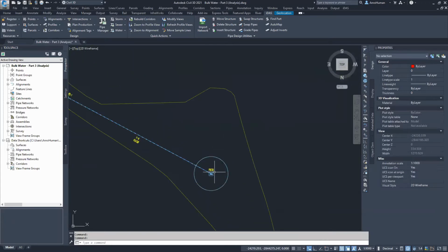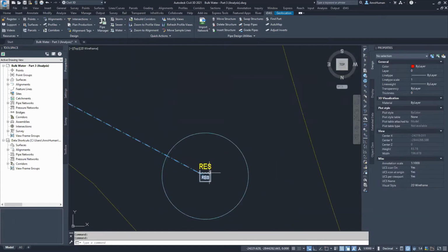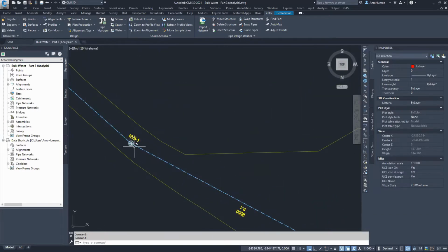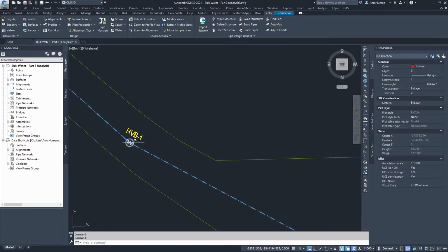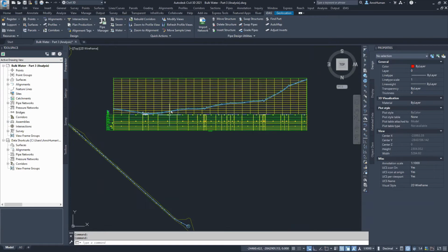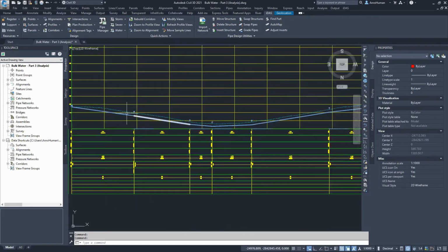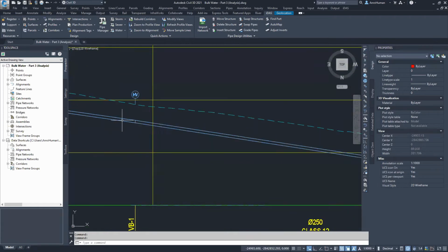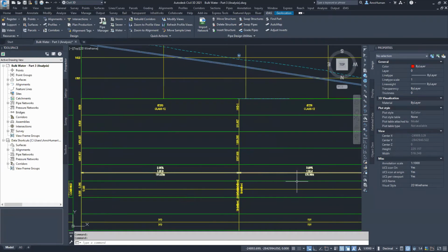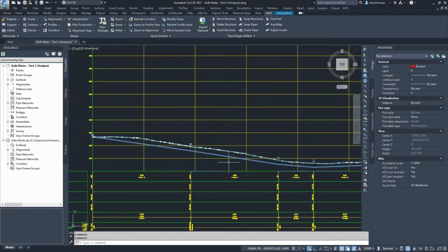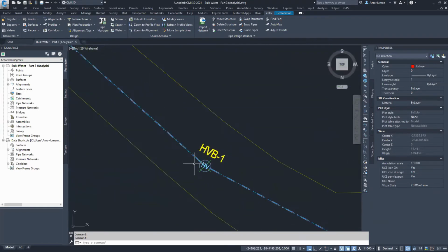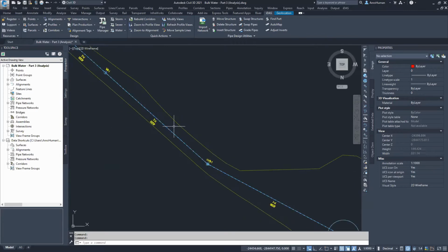All right, now as you can see, I've gone ahead and I've renamed all of my structures. I've also swapped these points to reservoirs. Wherever I have a change in the horizontal direction, I have added horizontal and vertical bends because these do change in slope between the pipes at these nodes. HV, as you can see, you do have a slope difference. There's a 2.85 and there is a 3.09%. Right, so this is what our vertical bends look like. Those are at the nodes or at the vertices on our alignment.